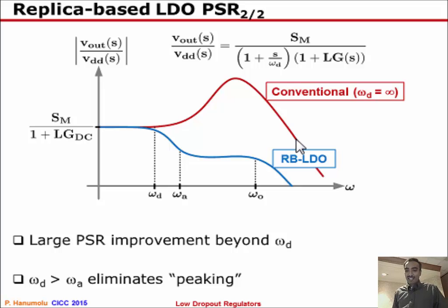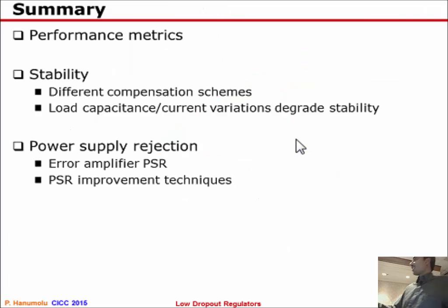And reference 8 shows one example for an oscillator, and if you have a static current like TIAs or any front-end stages that consume static current, then it's not easy but possible to actually come up with a replica that matches the IV characteristics of your load. Okay, I think this is all I have. We are up in our time.